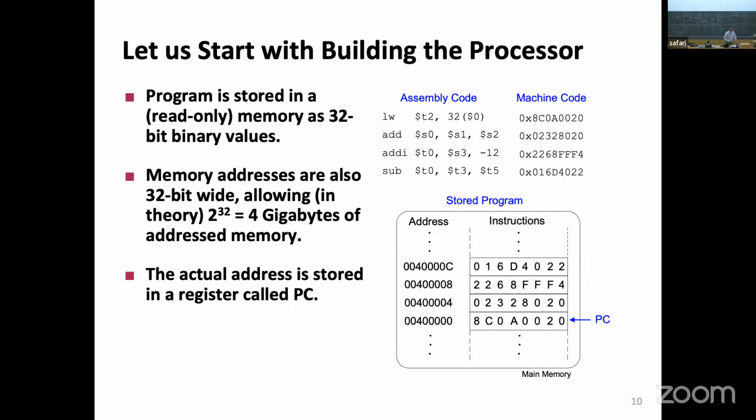Now, there are other very important things, because we realize that we are not manipulating this program counter at all. We are just staying where we are. Why don't we try to make something a bit more exciting? One instruction that we really have to have is a branch. We don't have to have all of them, but we need a branch. Let's try to do a branch if equal to. By the way, the branch not equal to will be very similar.